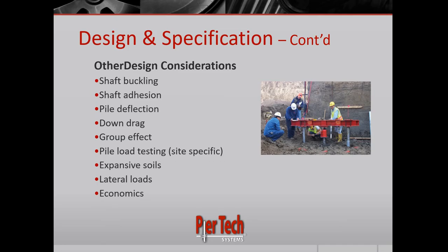Again, helical piles generally are designed just for axial loads and not for lateral loads. But we know there are some light loaded applications like decks and small outstructures that will require some lateral load. So you want to make sure you account for that in the design.